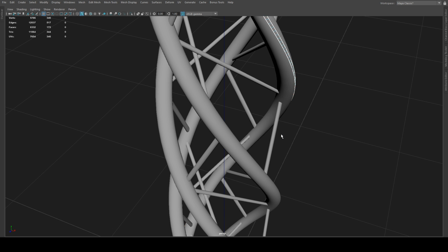So what I'm going to do is I'm going to grab the UV shell, and I need to normalize this. So first thing I'm going to do is I'm going to scale down, and I'm going to scale down a little more. I'm going to come over here, and now I'm going to normalize this. And what this has done is that it's now laid out in a linear fashion all of the 170 individual pixels, so that when I set my resolution in D3, I now have a screen that I can assign to 1 pixel equals 1 polygon for ArtNet values.